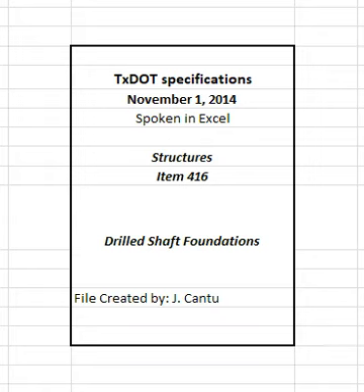Agitate the congealed slurry to liquefaction if the slurry forms a gel before concrete placement, and whenever directed. Recover and dispose of all slurry as approved, and in accordance with all federal, state, and local laws. Do not discharge slurry into or in close proximity to streams or other bodies of water.